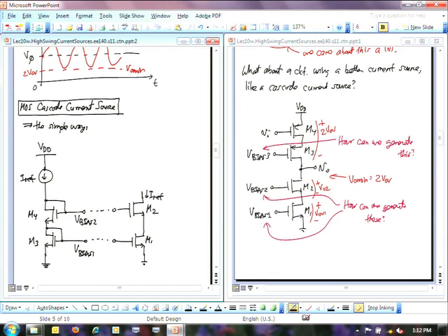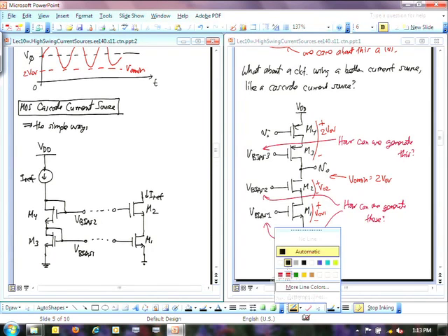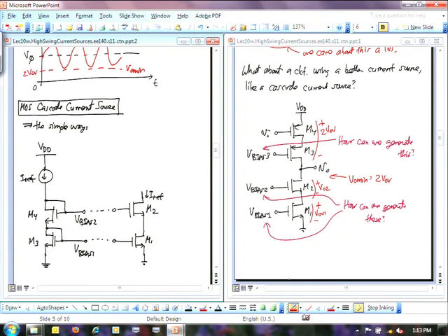Okay, so you can diode connect these guys, and how good is this, right? This works. This looks pretty good. What's the problem? Well, let's take a look. You know the problem is going to be associated with swing, because we just talked about dynamic range. We want this thing to have the maximum swing possible. That means we want this node here to be 2 VOVs, 2 overdrive voltages. Let's see if that's what it ends up being.